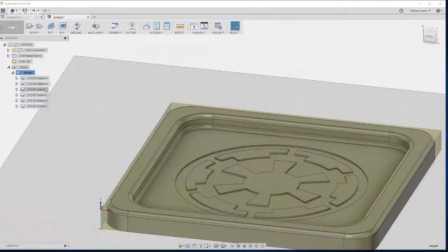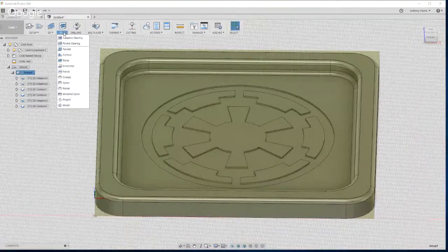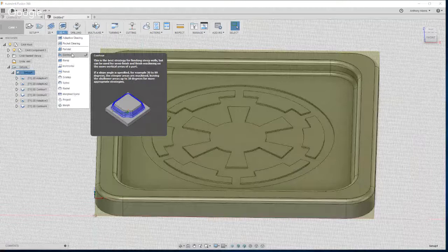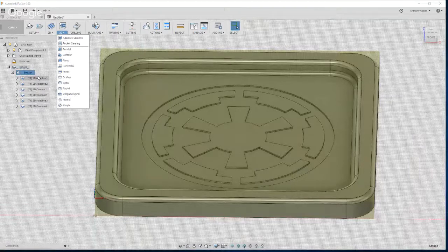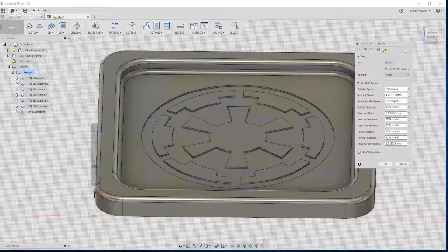I'm going to create a 3D operation. So now I have to come in and say new. You can't do a derived from 2D to 3D. It can't copy the settings over. So I'm going to do a 3D contour. Under 3D contour again, you would want to input your same 75 inches per unit and copy the rest of your settings on down through for this.